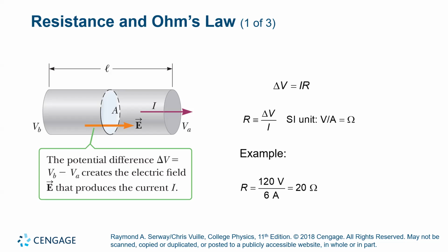Okay? And your multimeter that you use in the lab will assume that as well. The red lead of the multimeter is supposed to be placed on where you think the current is entering, or the higher voltage value. And the black lead goes on the opposite side where the current exits. If you have that wrong and the current actually flows the other way, your voltmeter will read a negative voltage because it's going to do VB minus VA.